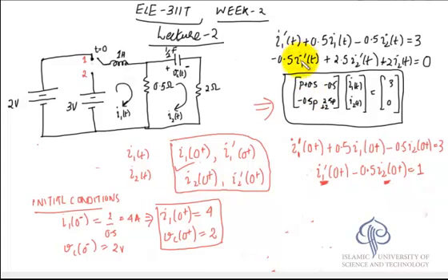Now let us see the second equation. Since we know the capacitor voltage at 0 plus, let us use this information to simplify the whole thing. We can combine the two differential equations by writing the mesh equation for the bigger mesh outside, and this would help us in solving the problem slightly more easily. So let us write down the mesh equation for the outside mesh at 0 plus. That is basically combining the two equations together and then putting t equal to 0 plus.